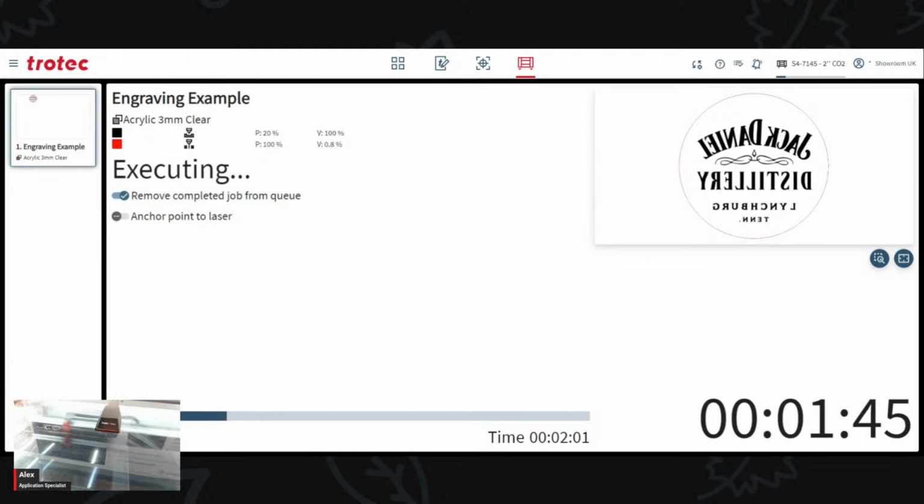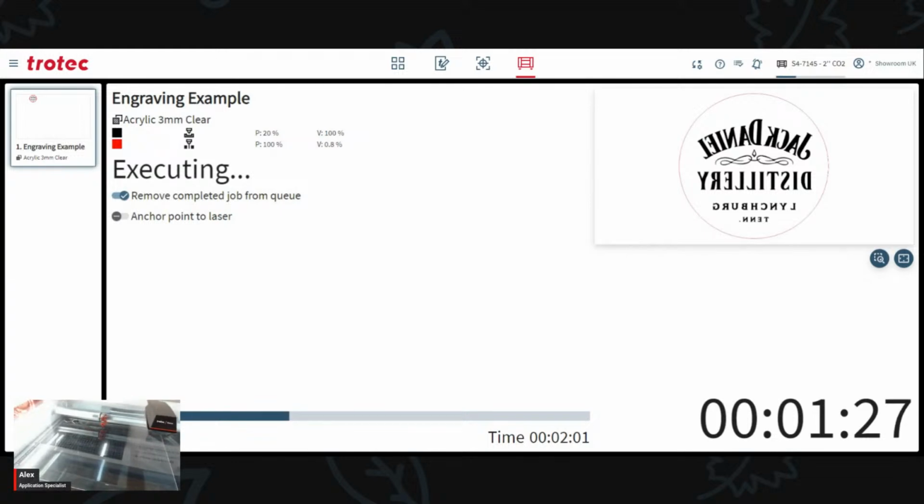So just looking at the way this material is engraving, this might actually be an extruded sheet, so you can sometimes tell by the way the surface finish comes across. But generally I find I just need 2 settings. A high quality setting, which would be just a little bit slower if you have really detailed imagery and shapes, and then a throughput setting as well. And again, you can color map all of these into one job. So it's really easy to do all of that.